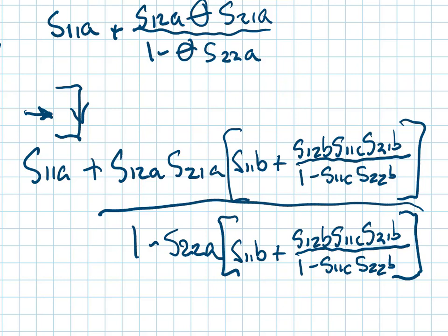Now, these techniques have been employed historically to come up with formulas for working with CAD programs. So deriving the formulas for combining S parameter, two ports in cascade, as we have done here, but also more complicated arrangements. And in day-to-day usage, if you work a lot with test fixtures in measurements, you can use these techniques to come up with an equivalent expression for the various components in your test setup to try to de-embed them. If you're using a test fixture, for example, and some other components ahead of your device under test, you can combine all of those S parameters together for the purpose of subtracting them out of the measurement at the end. Could be another application.